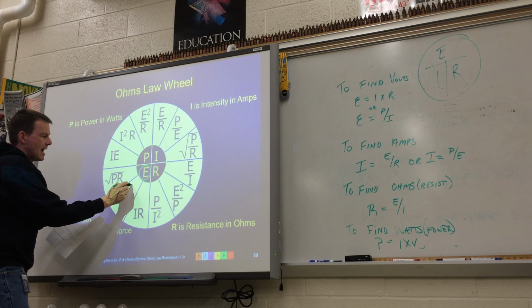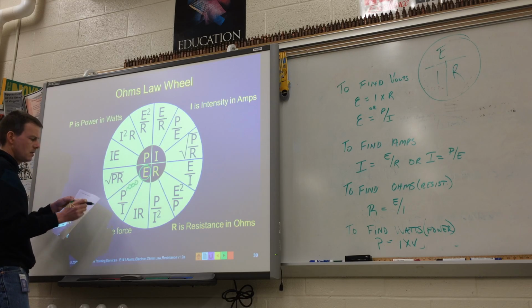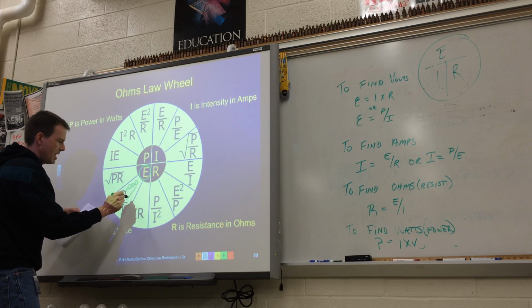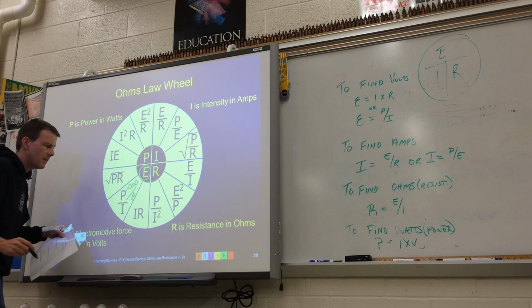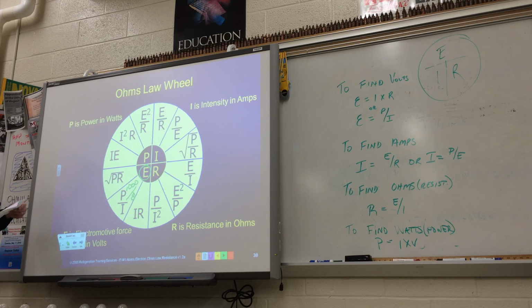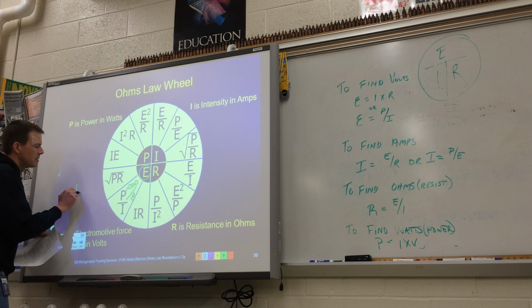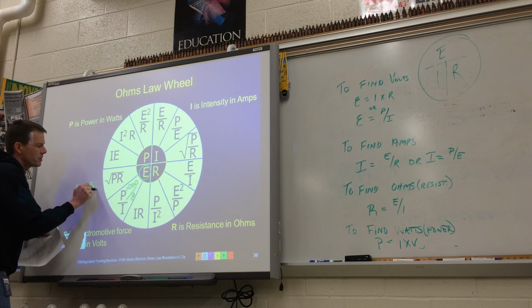All right, so you're given 1,000 here, power. And then what else were you given? Amps. All right, so 8 amps. So it's 1,000 divided by 8. What do you get for that? 125. So the first one for number 6 is 125 volts.